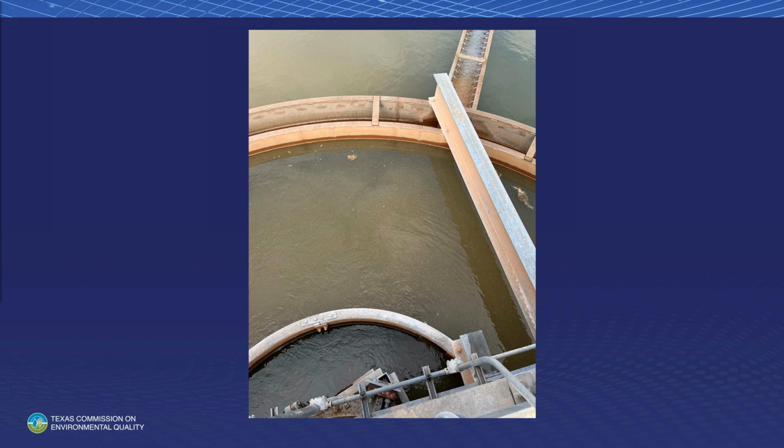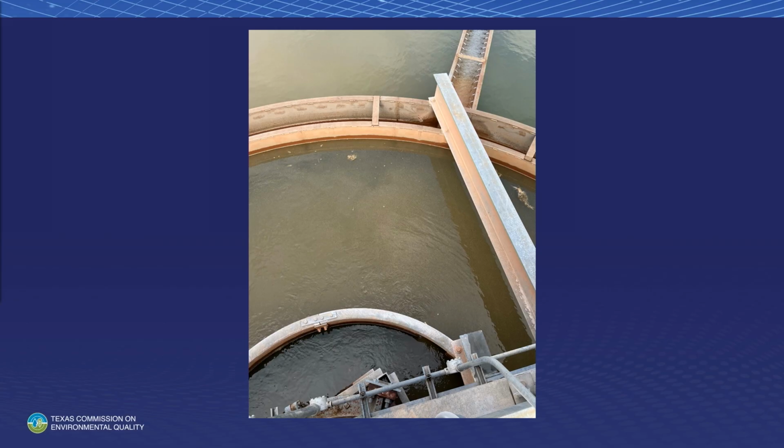We find that a lot. They just don't draw it down. Sometimes it's been so long since they've drawn it down that they can't draw it down, because the sludge in the bottom where the blow-off is has just congealed and is basically concrete. And what they have to do is go down there and break that all up and usually take it out with mud pumps from the oil patch in our part of the country. So sometimes the maintenance on things is just amazing.